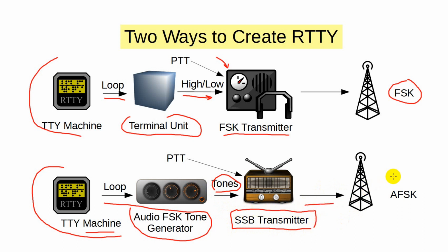Since this process is done using audio rather than directly, it's called audio frequency shift keying, or AFSK. Done right, this looks just like FSK on the air. By the way, the purists absolutely insist that AFSK just isn't an acceptable substitute for pure FSK. Done right, the two look identical on the air, and FSK and AFSK are completely interoperable. But note the caveat: done right, clean linear transmissions.